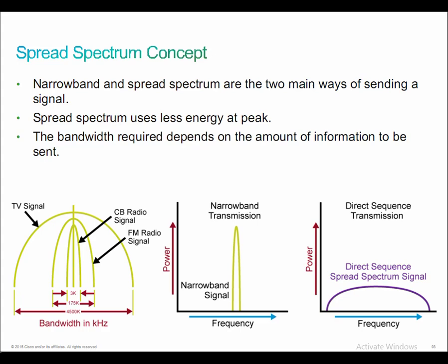If the first signal can emit in a range of frequencies or in a band, then you have some methods of eliminating that issue, right? You can prevent the signal from being jammed because we can simply jump to a different frequency, one after the other. That's what we call frequency hopping. Or the signal can be sent over a larger frequency range than the needed peak value of 2.412 gigahertz. So instead of sending at a specific tiny little frequency of 2.412 gigahertz, we decide to transmit over a range of frequencies within that range.